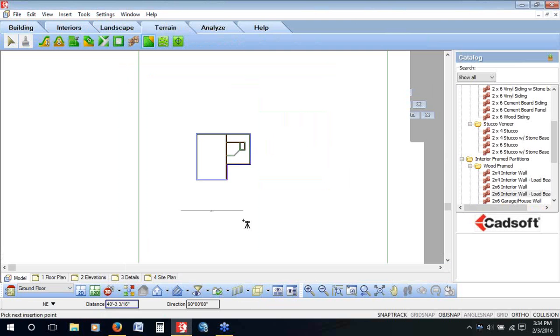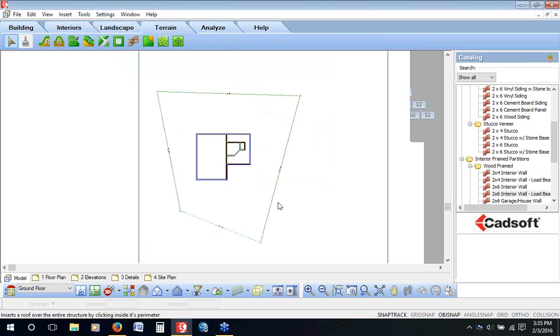For printing purposes, it's better for it to be in this orientation other than being at an angle, and you can always change them. So I'm just going to change the angle. So I could have my site plan doing something like that. That's the orientation, that's the house sitting on it. And then when I put it onto a working drawing sheet, I can insert a north arrow pointing north where it would actually be.